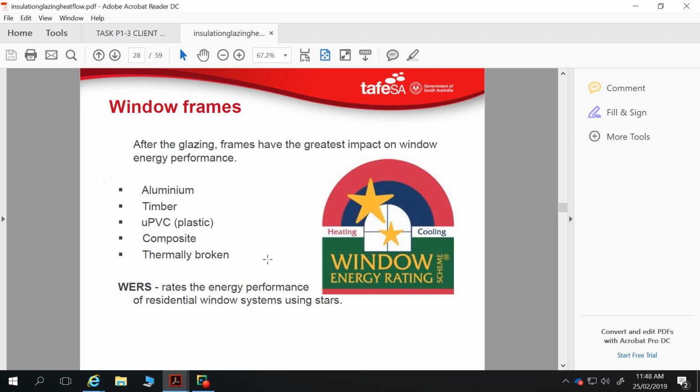You've got that maintenance, but they transmit less heat, though they can be draftier than your manufactured aluminium. Aluminium can be extruded very neatly and formed very neatly with incorporation of rubber seals, much easier than timber can be. But yeah, you've got aluminium, timber, UPVC windows, and they're actually relatively common. PVC window frames don't really stand out too much from your aluminium. It can be hard to pick.